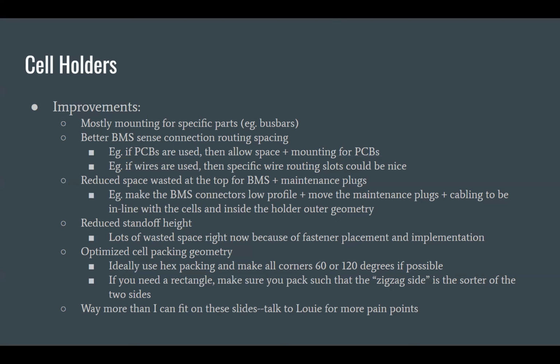But the problem is that the PCBs were complex to design because they didn't have mounting and were not intended to go there in the first place. So we had to make these spaghetti noodles you see in here that run up and down. We have these 5 millimeter wide strips that run up our pack. Ideally we could have had a cohesive battery PCB design from the beginning that just ran down the side, very easy, and just bolted through. Hindsight is 20/20, and if we had thought of that, it would have been great. We didn't. Instead we had to fit it to a slot that was originally designed for a bunch of wires to go through instead of a PCB. Fun times.